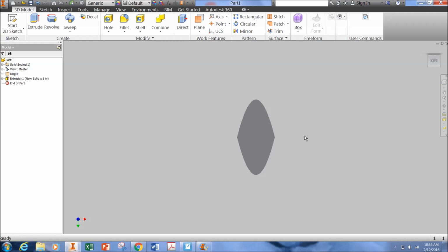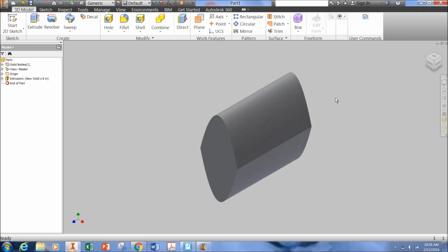I'll readjust the view so you can see the plane we must create. We'll go through these 2 points and all the way back and along. First, we need to select the plane tool. If we move our cursor over the intersection of the XY plane curves, you will see a yellow point indicator appearing.